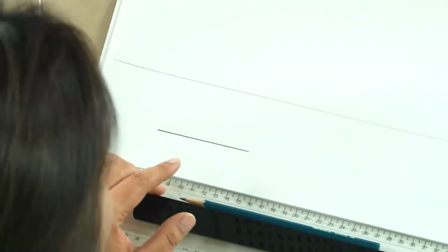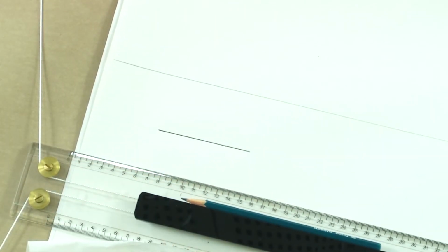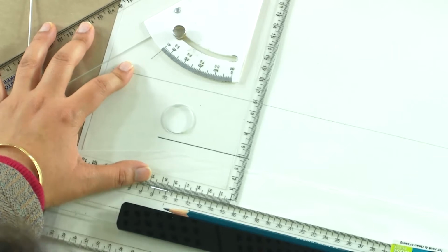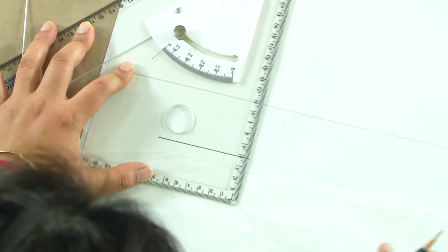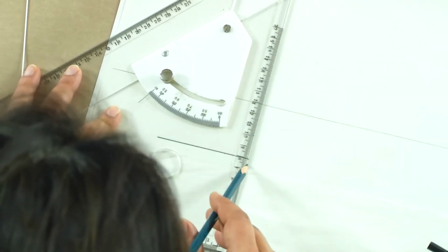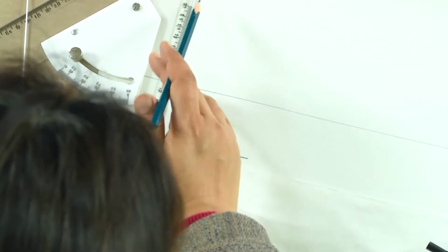We should always be careful about the thicknesses of the lines that we are going to be using. So for darkening, I have used a 2B pencil. Ideally, we should not be darkening directly. You should always draw the entire drawing in light pencil, say 2H first. This is 2H in my hand. Once we have drawn, we could start from the front elevation also or plan also, simply because in our case the line is parallel to both the planes and we will be seeing the true length of the line in both the views. So we could start from the elevation as well as the plan.